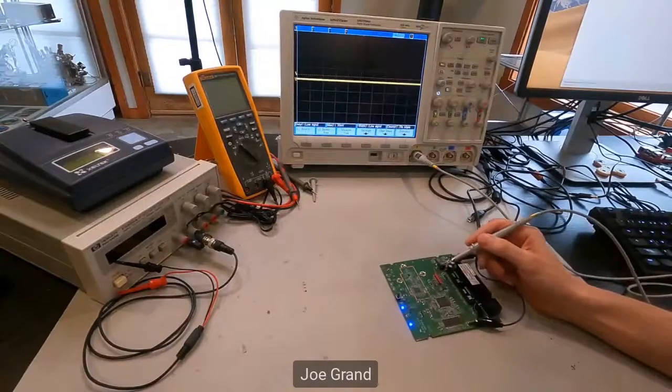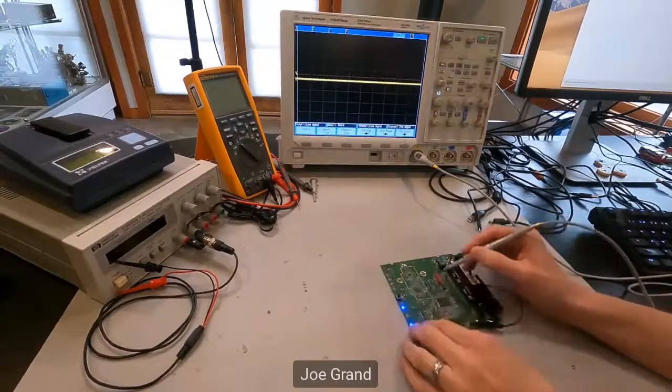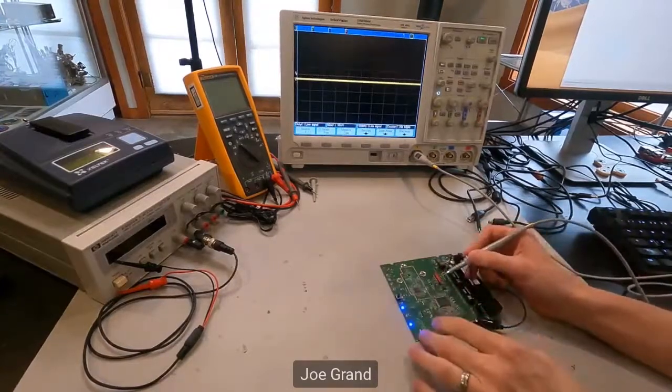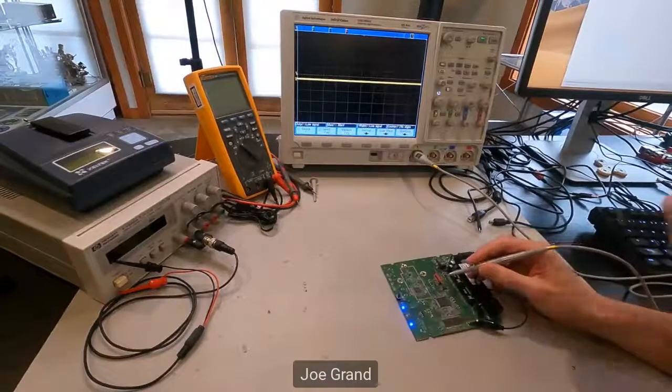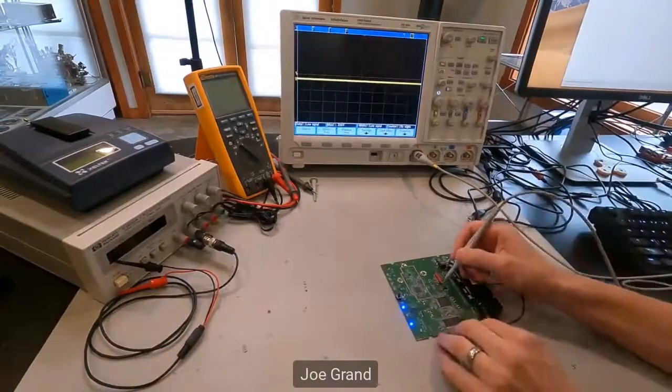That type of stuff really happens on power up. So when we're dealing with a system that we don't know, we want to make sure that we not only run it in this state where it's already powered up, but we want to start looking at signals and then plug in the board. Because on power up, we're going to see a lot of activity. So let's actually go ahead and do that.